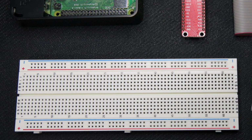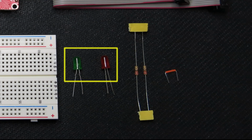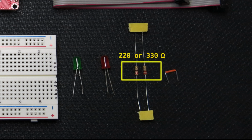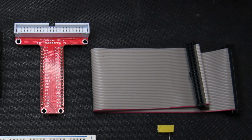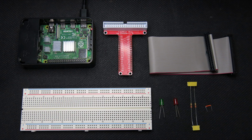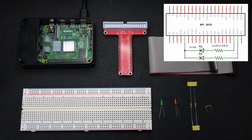You need a breadboard, a couple of LEDs, any colors, 2 resistors, 220 or 330 ohms, and a small jumper wire. You also need a way to connect the breadboard to the Pi. I will be using a T-coupler with a ribbon cable, but you can also use individual wires. The circuit build is very simple. I will walk you through the steps right now, but I assume that you know how a breadboard works.